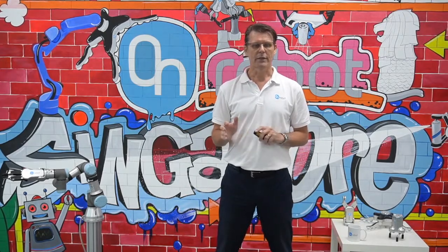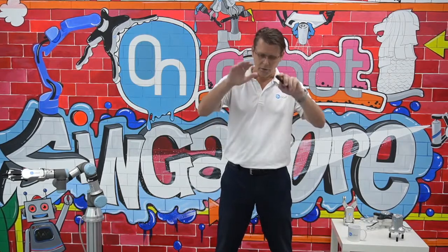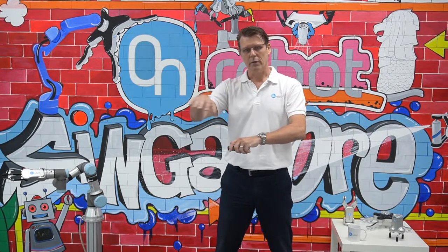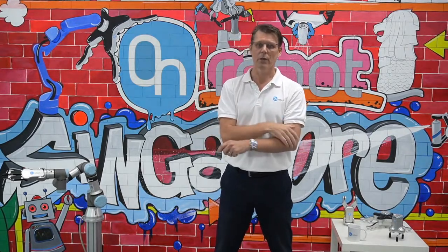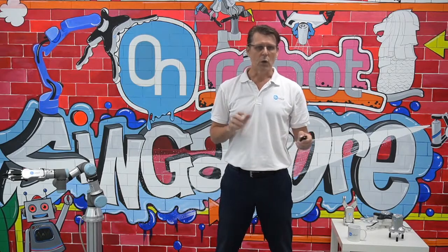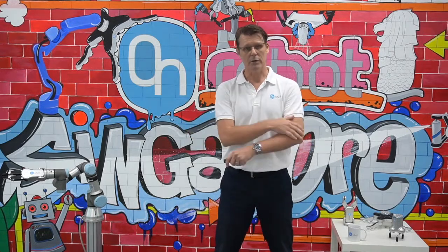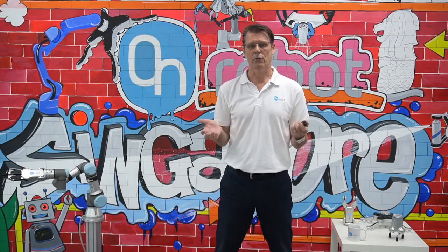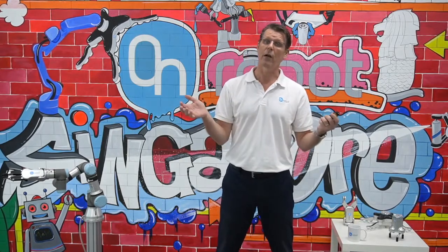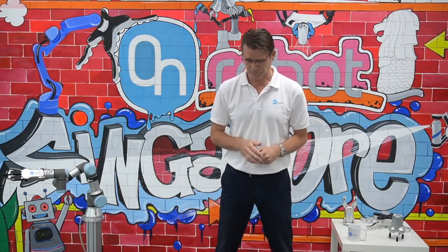When it comes to cobot safety, it typically relies on lightweight materials and rounded edges, so when the robot or the end effector on it moves around, if it hits somebody, it's not going to cut you. Mostly there's also a limitation on speed and force, because when it hits somebody it shouldn't hurt or damage humans or even equipment around the robot setup. Often that is done with various types of sensors and software.